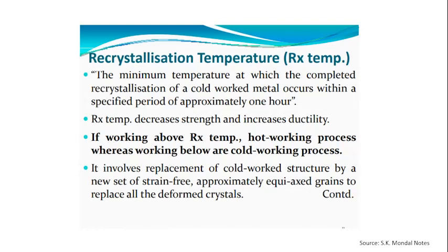Suppose you have cooled your material to recrystallization temperature; after 1 hour at that temperature, it will be recrystallized completely. Working above it is hot working, and working below it is cold working.